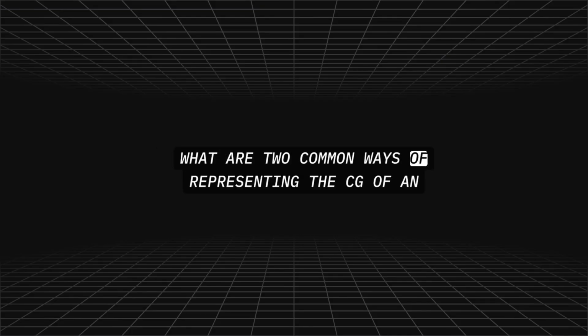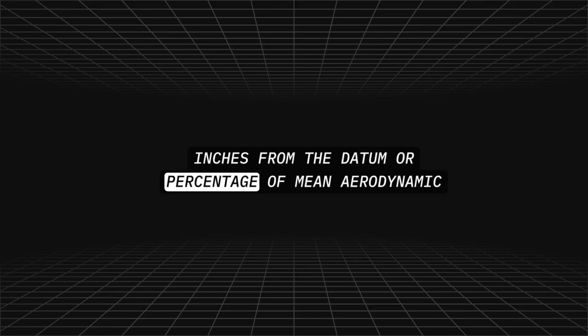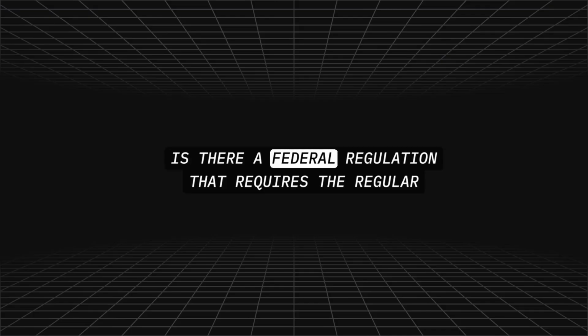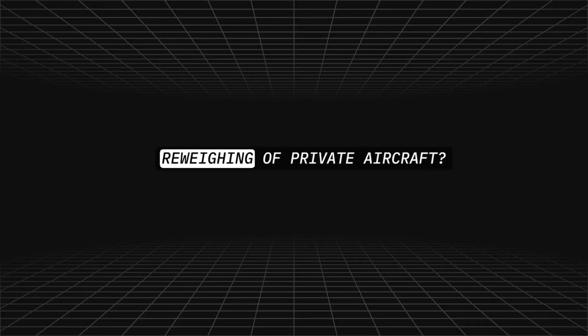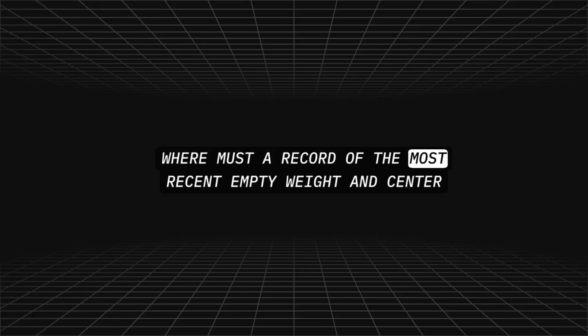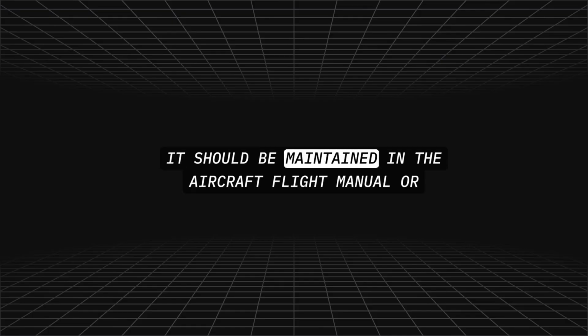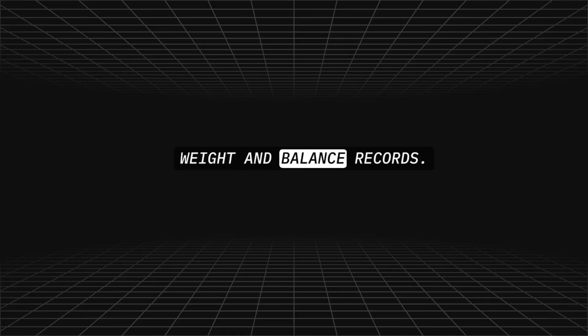What are two common ways of representing the CG of an aircraft? Inches from the datum, or percentage of mean aerodynamic chord, percentage of MAC. Is there a federal regulation that requires the regular reweighing of private aircraft? No. Where must a record of the most recent empty weight and center of gravity be kept? It should be maintained in the aircraft flight manual or weight and balance records.